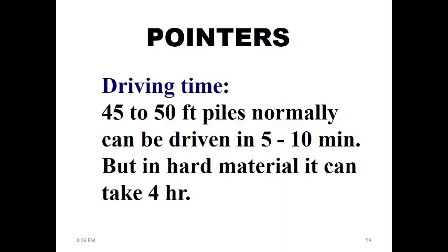The process can be really fast or it can be really slow to drive the piles. If the conditions are good, then 45 to 50 feet piles will be driven really quickly, within 5 to 10 minutes, but for hard materials, for hard cases, it can take 4 hours for just one pile. Now imagine the scheduling process if someone is not aware of this information and they simply plug in some numbers. And there are projects where you have thousands of piles that you have to drive into the media.